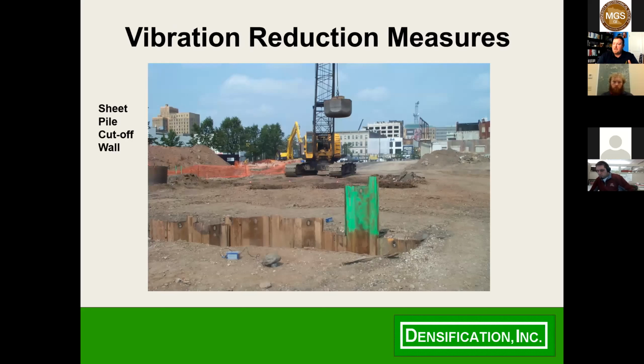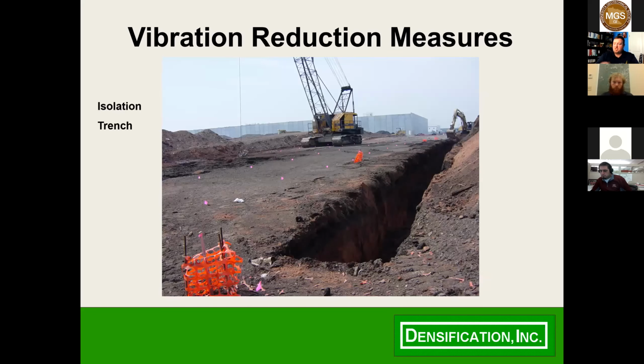Here you see a couple of examples. This was an instance where we tried out sheet piling as a vibration mitigation tool. This is probably the most common seismic isolation trench, where if you're dropping on one side and you're trying to isolate the vibrations to something, a utility or a structure on the other side, this helps mitigate your vibration levels